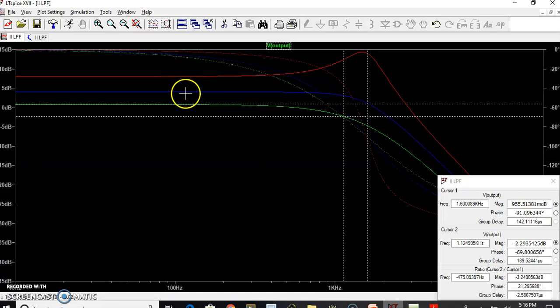That's why we call this gain, which corresponds to a Q of 0.707, a maximally flat response. For a gain more than 1.56, you can certainly see there is an overshoot response, which is not good for many applications. So in the case of a Butterworth second order filter, for a gain of 1.56, we get a maximally flat response.